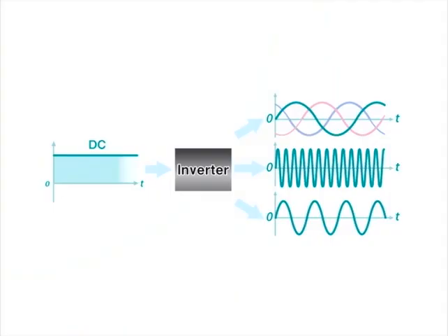The inverter is a power converter designed to convert DC to AC. The output AC voltage is not limited to 60 Hz. The inverter can output frequency as required by the load, for instance from several hertz to 100 kilohertz. It can output not only single-phase current but three-phase current as well. What's more, the amplitude of AC current can be adjusted.